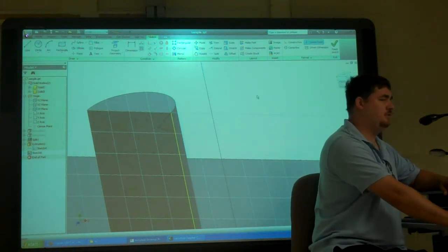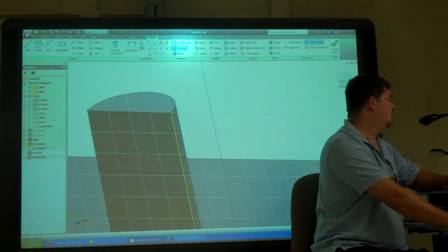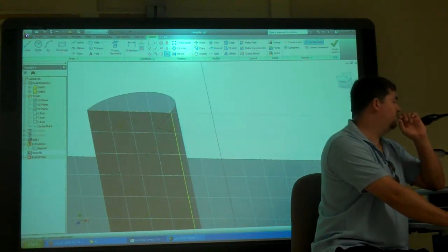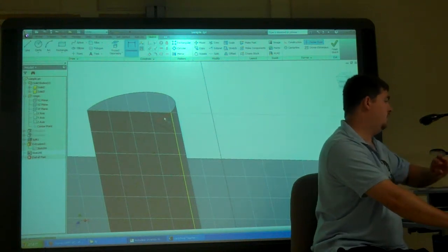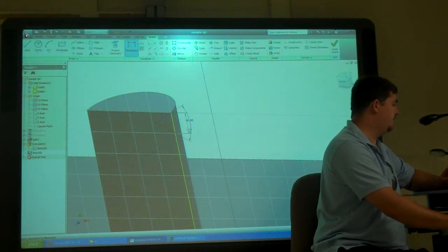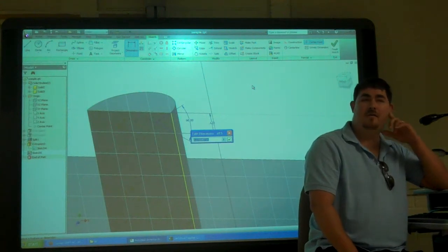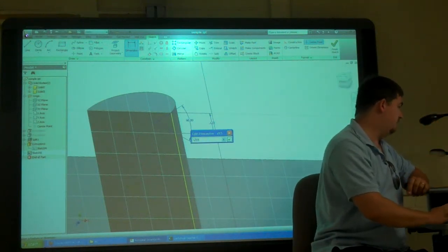So what is a tooth supposed to look like? What's a thread supposed to look like? Yeah, the general tooth itself. Sides going to be equal, right? What is that angle in there? 60. Yep, 60. And then what's this distance here? If I want to do a half 13 thread, what would that distance be? 1/13. You just take the threads per inch, invert it, so you get 1/13.